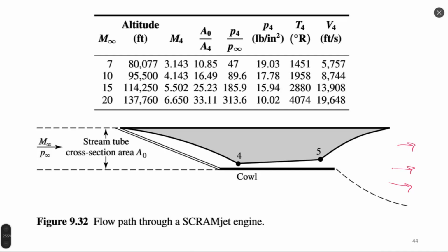In such a case, this nozzle is not a symmetric nozzle. Expansion happens due to increase of geometry on just the upper part. Here, the lower part does not exist. So there is non-symmetric expansion, which generates a significant value of thrust and allows movement of such a flight vehicle.